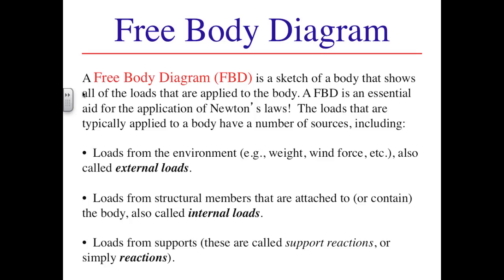The process we described in Chapter 3 for approaching and solving particle equilibrium problems will also hold for rigid body equilibrium. As a reminder, this slide from Chapter 3 has been reproduced here. Before writing any equilibrium equations, it is important to visually isolate the body of interest, drawing an enveloping surface around it and including three classes of forces, and now moments, acting on the body. External loads from the environment, often weight, internal loads exposed when we cut through connected members, and reaction loads.